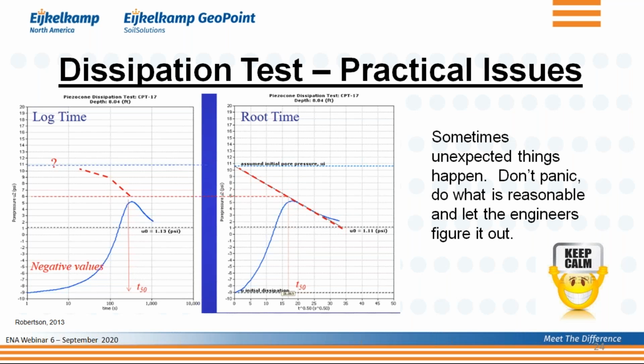The answer that I have to people like that is, again, don't panic, take your time, wait until you get the peak here, and then start recording about once a minute what the pore pressure is, and then call the office. Call the engineer that is in charge of this whole thing, because that engineer has some additional tools.